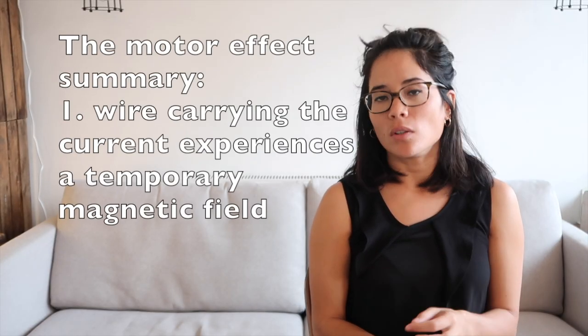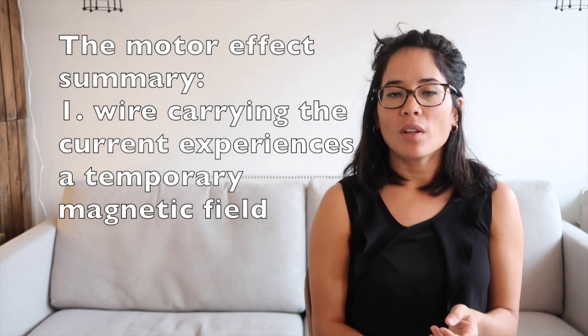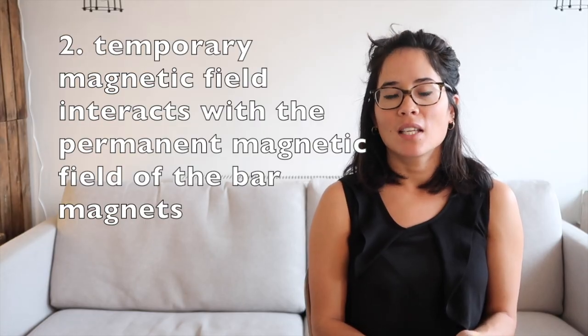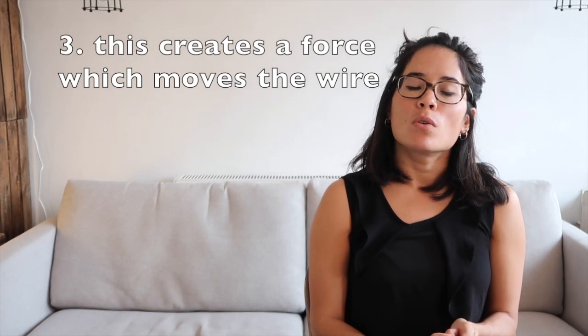So in terms of answering the 5 markers, which tend to be something like a wire is placed within the magnetic field and a force is felt, discuss. It's worth 5 marks. So it doesn't matter how they word up these questions, the answer is always the same. You want to start by saying the wire carrying the current, so your coil, has a temporary magnetic field, and what that does is it interacts with the permanent magnetic field of the bar magnets. This creates a force causing the wire to turn, and believe it or not, this applies as well when you're talking about a loudspeaker, because anything that moves in and out in this way involving magnets will use the motor effect, even though it doesn't seem particularly obvious.